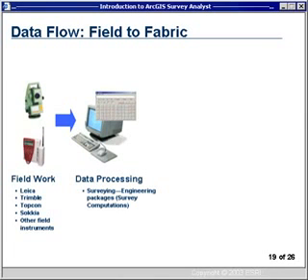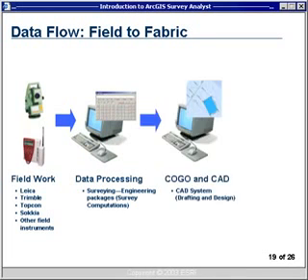In this process, survey computations are used to resolve the raw measurements into positions. Once the first computation is done, the data can then be adjusted. You end up with adjusted locations or resolved positions of survey points. Oftentimes, the next step in this process is that data are entered using COGO into a CAD system. And within the CAD system, certain drafting and design work takes place. Oftentimes, some of these packages do more than one function.